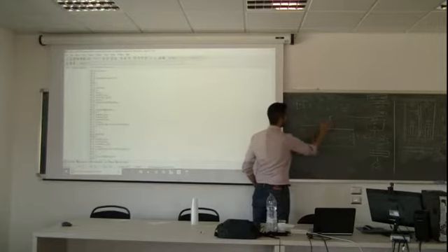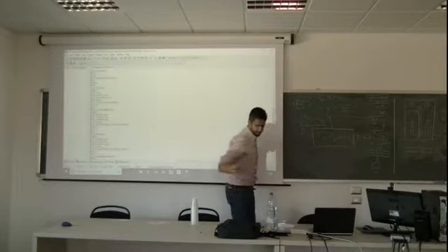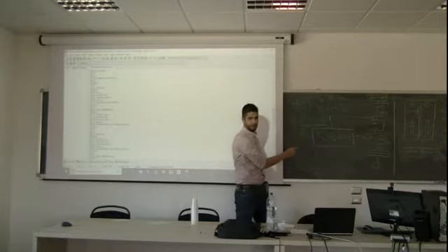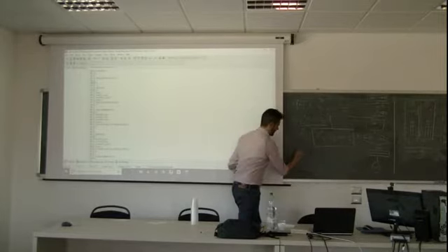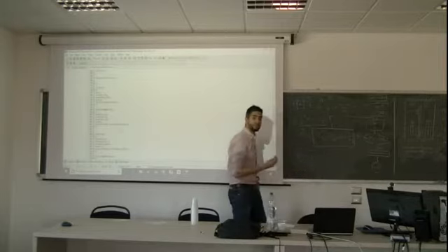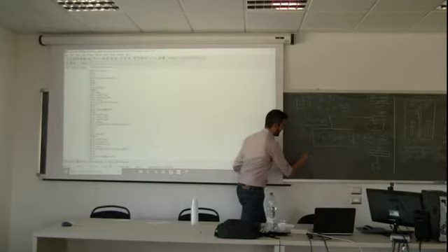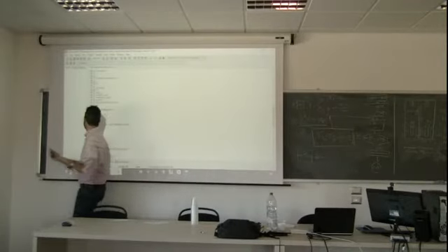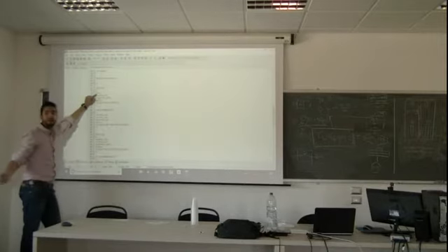Now, I say this is the C coefficient, this is the D coefficient, and this is the A coefficient. Because in this case we have only one conduction. If we have another conduction, we will have more terms in the denominator, as we had in the past. So, when I face one node, I usually say the coefficient that comes from the west, I name B, this is C, and this is D. And the denominator will be A. Okay, in this case, B is equal to 0, there is no B, because it's adiabatic.